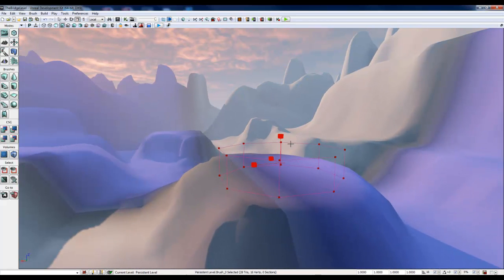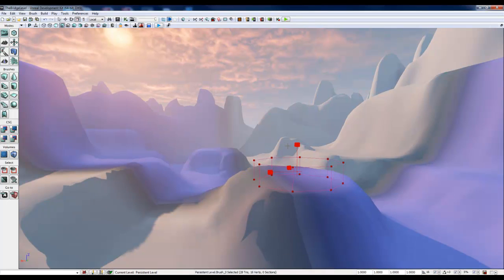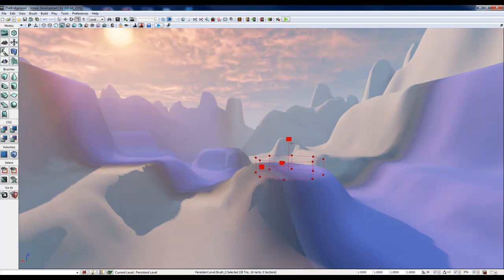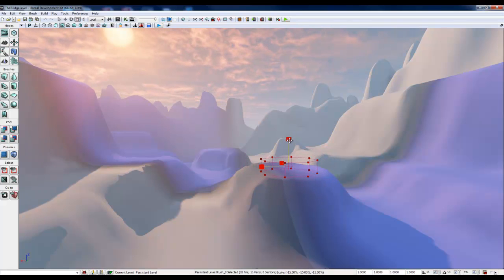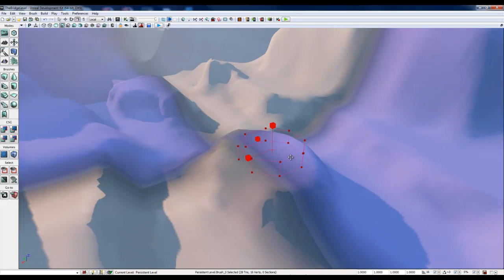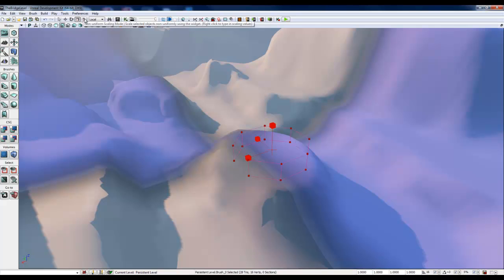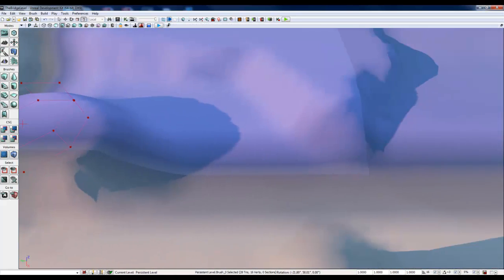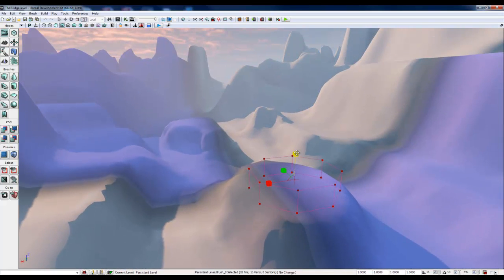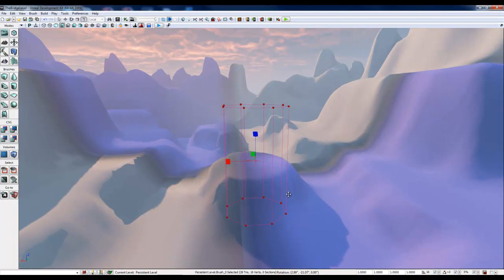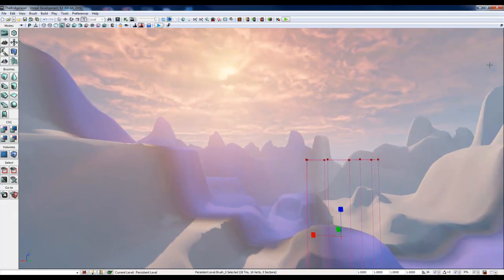Now, to put this additive geometry in, I want this to be tall. But if I scale it, it scales everything. So how do you do that? Click on this non-uniform scaling mode. And now, as you see, the handles change and they have different colors. If we grab this top handle and pull it up, we're able to stretch it just like we want.